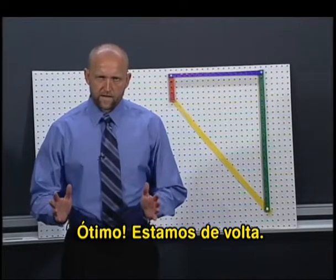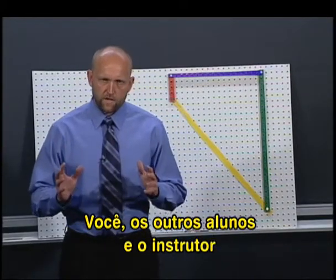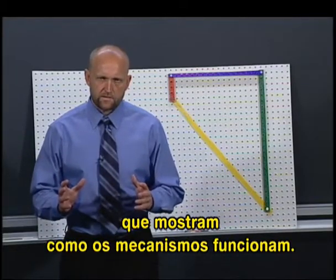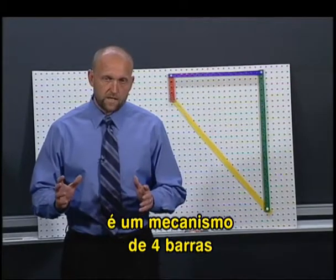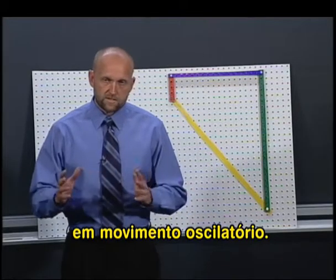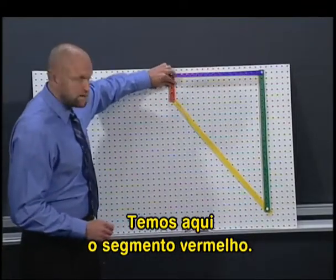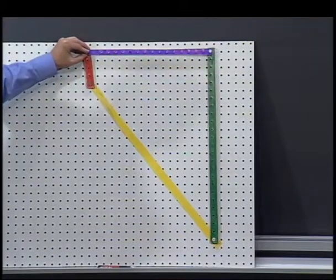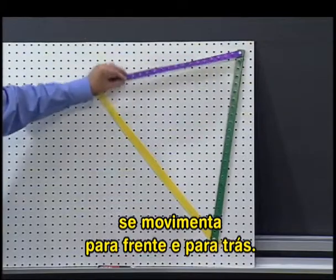Great. So you're back from that interactive work session, and you and the other students in the room and your instructor have been building actual physical prototypes that show how mechanisms work. And what you've seen is that one of the things you can do is make a 4-bar mechanism that converts rotary motion into essentially oscillating motion. What we have here is the red link. If it goes around and around, the farthest end of the green link essentially just goes back and forth.